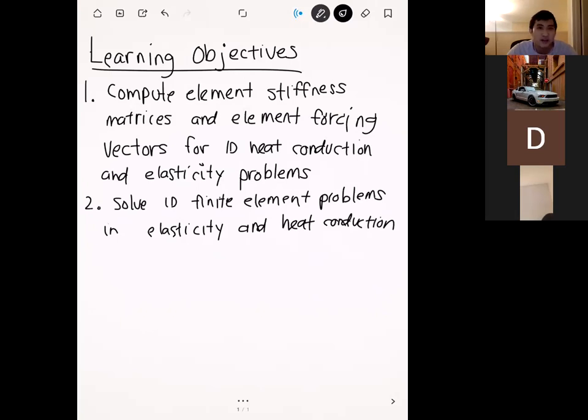Right? Technically, in ANSYS activity 2 I gave you an assembly too, but we suppressed everything except for one part. On Tuesday, what you'll see is how you actually work with an assembly, how you can assign different materials to different parts, and probably most importantly, how you define the connections in between the different parts of an assembly. Okay. I think that's the most important thing to take away from Tuesday: when you have multiple parts that you maybe created in an assembly in SolidWorks, you have to define how those parts are going to interact within the finite element simulation. Okay.